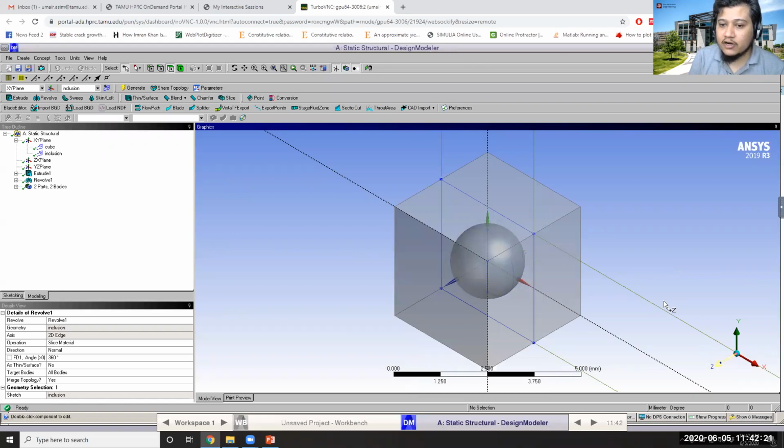The answer for our current problem is yes. Since we are using isotropic elasticity and isotropic hardening as well, we are assuming that the mechanical properties are the same in all the directions. We can make use of these symmetries. You will encounter certain cases. Just give me a second.